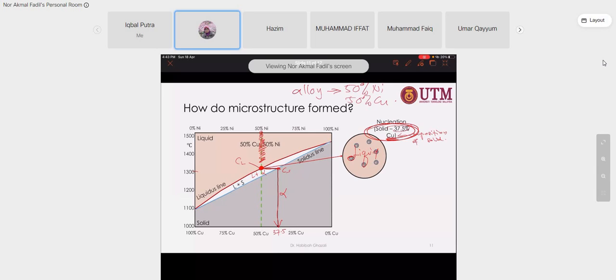Why is it 37.5% copper? In fact, our alloy contains 50% copper. It is because of the diffusion phenomena. At this point, when nucleation begins, it is rich in nickel, with only 37.5% copper. Later, when you solidify 100%, if you draw a lever rule